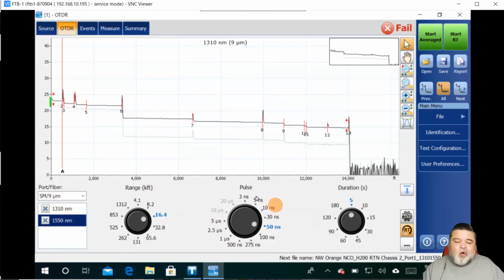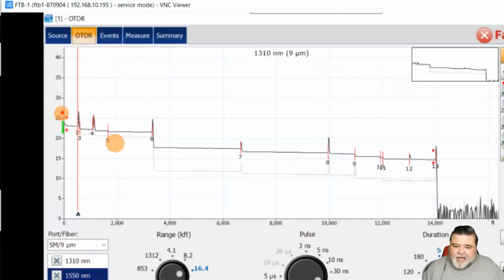And when it comes to pulse width, just drop it down as low as it'll go and still clean up at the end of the duration. And that's really what you do with an OTDR. And then inspect and clean, like it's the most important thing in the world, because it literally is for a lot of this testing. If I look at a trace and I see it launch with a ski slope, or after a reflection, I see a ski slope, this is bad.